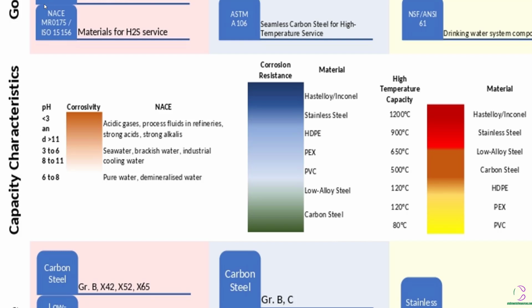Also, these are extremes. For example, there are some pipe materials that can handle the extreme of corrosivity. But what you probably need is a medium to high level of corrosivity resistance, in which case the acid or the alkali is at a low level, but it is present. So that's when selection of different materials and retrofitting them to meet the required properties come into play.